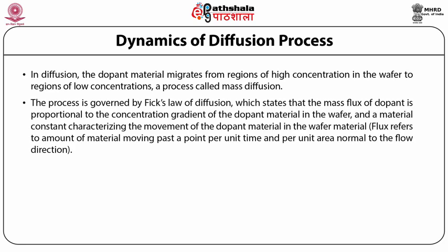So the process is governed by Fick's law of diffusion, which states that the mass flux of the dopant is proportional to the concentration gradient of the dopant material in the wafer and a material constant characterizing the movement of the dopant material in the wafer material.